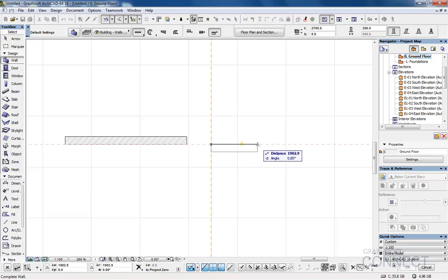But you'll see, because I've played with the construction line, it's actually on the wrong side. Now what I don't particularly want to do is move the mouse to the top of the screen. So because it's the construction line, I can just press C for construction, and you'll see that that goes through the 3 options. So you can press it as many times as you like, you're just going to get a sore finger. But we cycle it around so it's at the correct side, and then I just type in whatever my new dimension is, press enter, and that's it, finished.